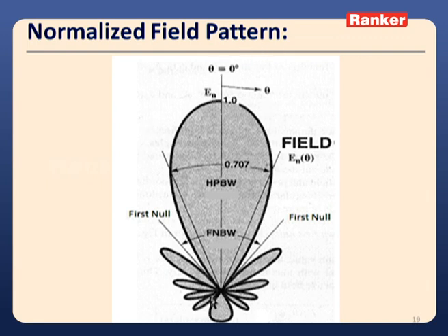Now this is a major lobe, and all these are the side lobes that we have. This is the first null. First null means the null which is adjacent to the major lobe. This is also the first null, the null which is adjacent to the major lobe. Now clearly remember, I will define two important parameters. They are called half power beam width and beam width between first nulls. That's also called first null beam width.